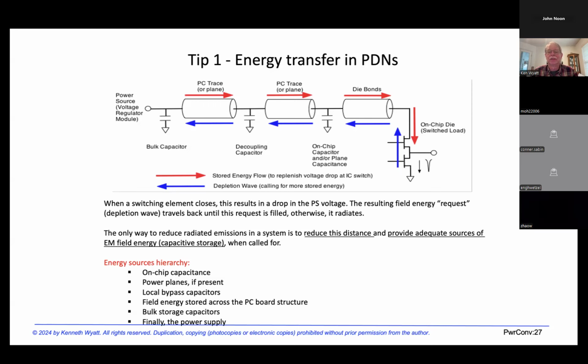And so we want the power distribution network to be as low impedance as possible. And I see some designs putting ferrite beads in line with the power distribution network. And the reason I don't like to see impedances added is because it's going to affect the performance of these energy storage capacitors. So keep that in mind when you're laying out power distribution.